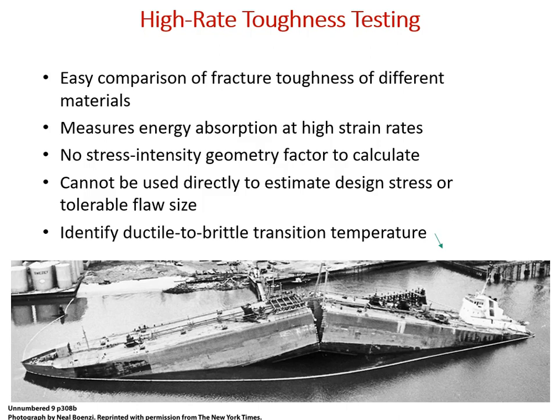So now we're going to move into high-rate fracture toughness testing, which is basically the quick and easy semi-quantitative means of assessing fracture toughness of materials when you don't have time to do the very intensive repetitive testing necessary to establish a true K1C. And then we will address creep and fatigue, which are two more insidious means of material failure that ultimately results typically in fracture or ductile overload.